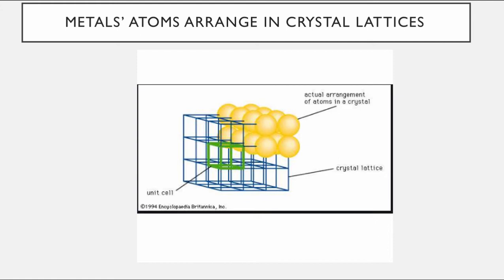But what's interesting in this particular configuration, which makes the unit cell look like a cube, those atoms are configured in the loosest possible configuration where they're still touching. All the rows, all the columns, all the layers are all perfectly aligned, and so you have very large void spaces in between. In real life, the different rows could be staggered so that one row nests inside the other row, and the layers could be staggered again so your atoms nest in between in the little openings, as if you were trying to stack balls. You wouldn't stack them on top of each other, you'd stack them in the little pockets in between.